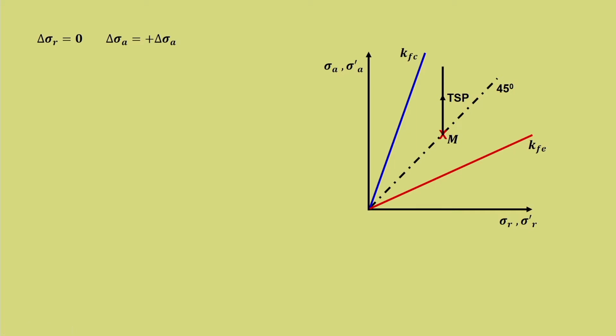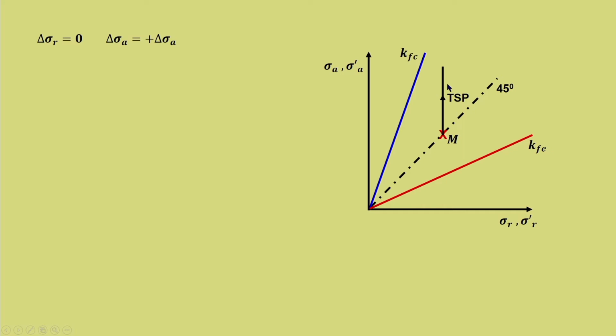Now, this is very much similar to the drained triaxial stress path for the same condition. So, the total stress path in both the cases, the drained and the undrained, is not going to change. But you may be wondering, why did I stop this total stress path at this particular point? Why is it so? And there is a discontinuity here.